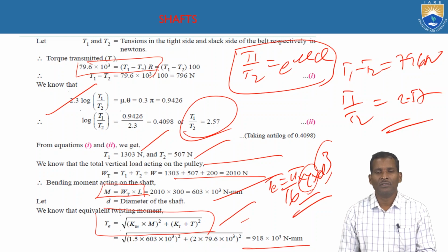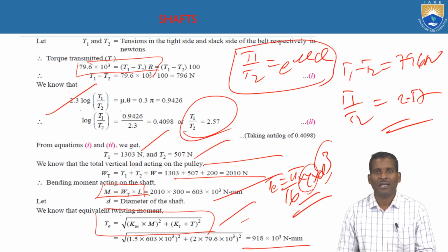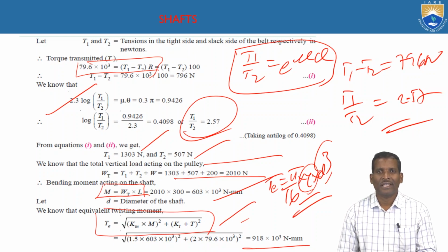So why? Because the shafts are subjected to cyclic loads. So after some time, after number of cycles, the component will fail. The shaft or component will fail due to this fatigue loading. These cyclic loads, this phenomenon is known as fatigue load, fatigue phenomena.